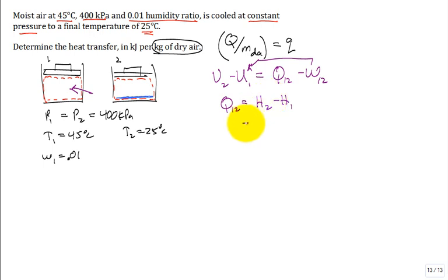So now all we have to say is, I have a change in enthalpy. Okay, we'll bust it into two components. Let's consider the mass of dry air that's trapped in the system. And it's going to end at enthalpy 2 and start at enthalpy 1 of the dry air. And we're going to have the mass that's a vapor. But I'm going to bust that mass of vapor into two things, because after the end of the process, I expect there's some liquid. So I'll have the mass of the vapor to begin with, state 1, V1. But at the end, it's equal to the mass of the vapor that's in the vapor state, plus the mass that may have condensed, now liquid at the bottom of the tank. Does that mass balance for water make sense?